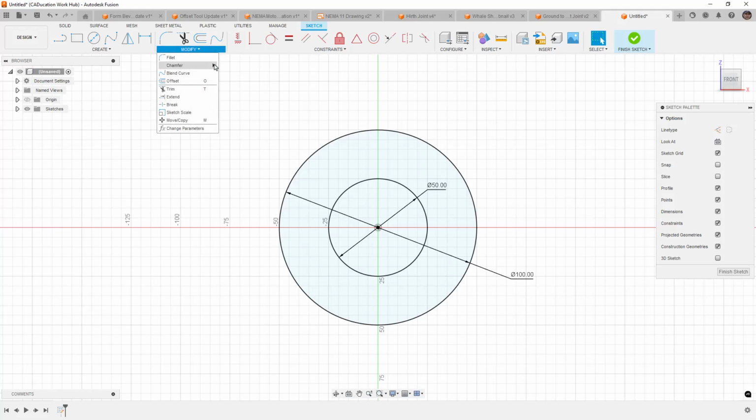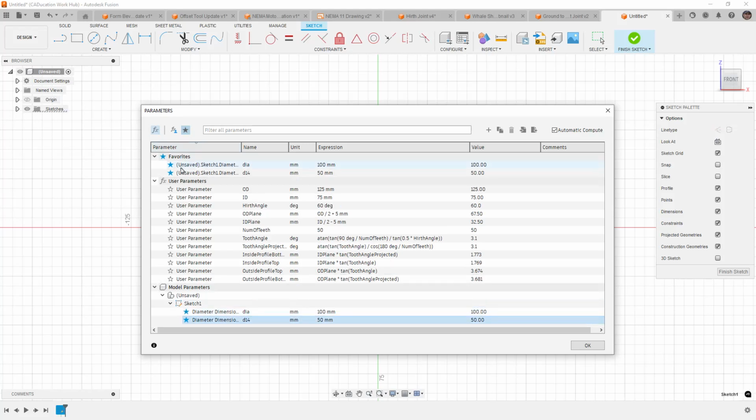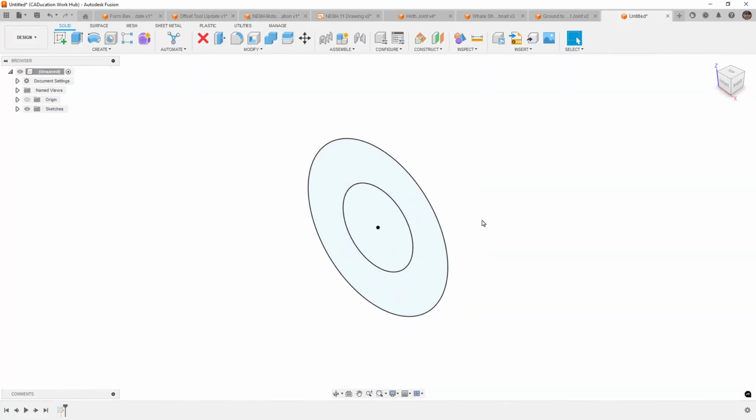And once again, the way that this works is you are not creating a user parameter. What you're doing is you're creating a favorite saved value. So this is different than a user parameter. This still appears in the sketch. And what ends up happening is it basically just adds the star and puts it in your favorites list. So if you're trying to do this to import or export parameters, it's not going to help you. You really still do need to create those user parameters globally inside of that dialog first. But those are the improvements that we have to the parameters.